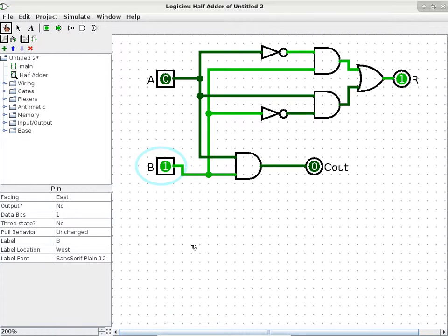And the flip side, symmetric, okay? So the only really tricky case is when A is a 1 and B is a 1, then the carry should be a 1 and the output should be a 0. So we do it here. So now I have just verified every single case for a half adder. Do we have any questions at this point?